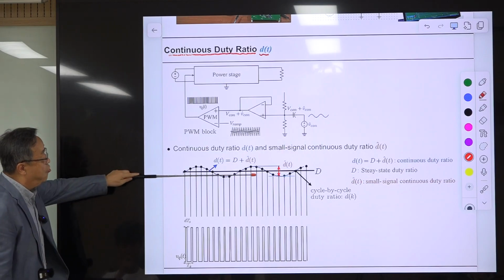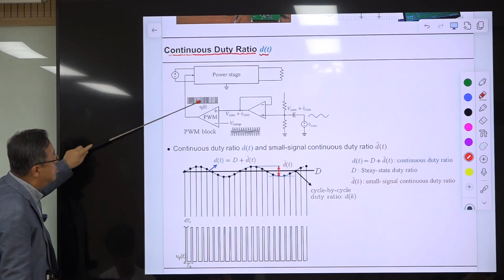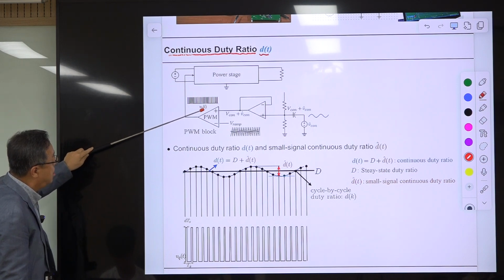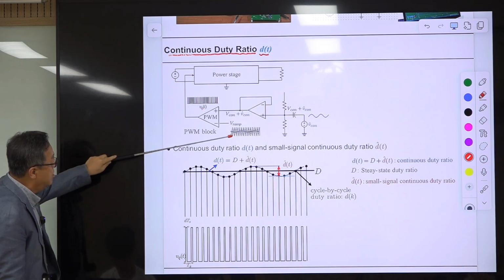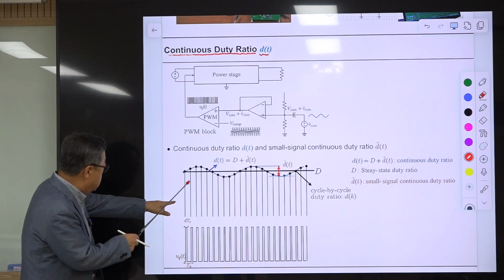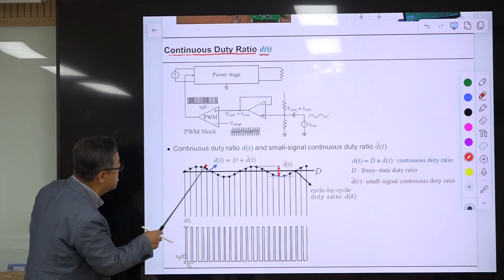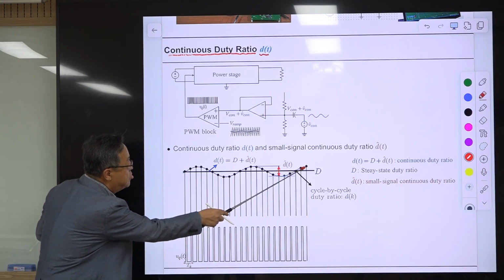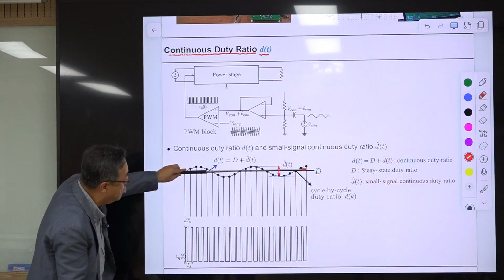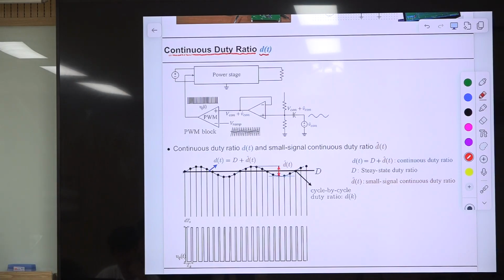Let me explain this first. This is the pulse width modulated switch drive signal vQ(t), and this is the generation of that signal. We are comparing a ramp with this sinusoidal waveform on top of this DC value, and we evaluate the duty ratio. Forget about this first one.